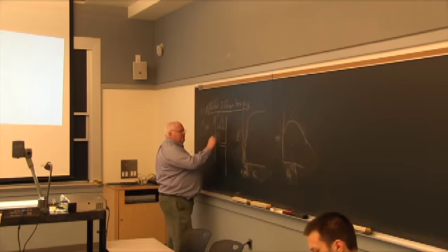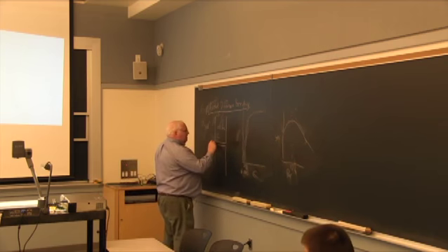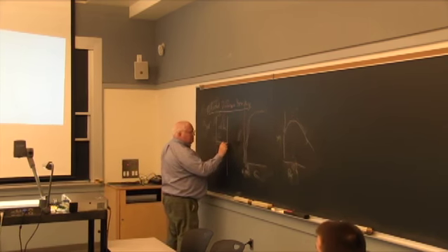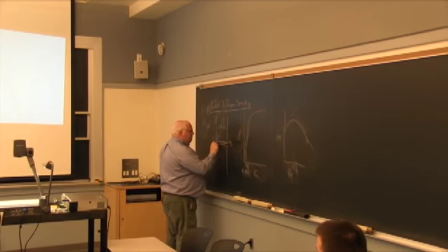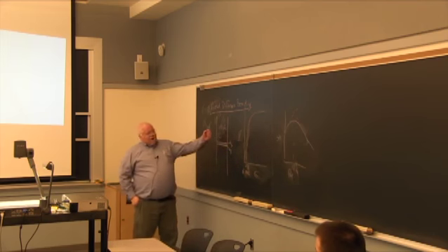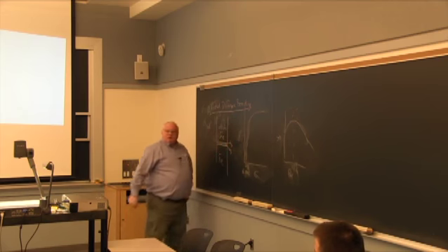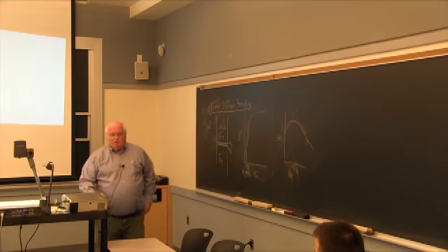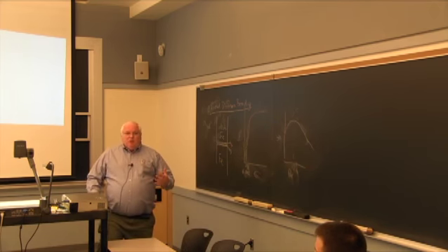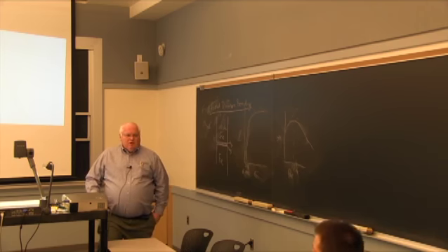And then there are other things in here rather than just iron, but you have oxides on the surface that won't let you diffusion bond at low temperature. So what O'Brien, Rice, and Olson did is they basically deposited a layer of silver on both of these. They call it activated diffusion bonding, but now you're not bonding iron to iron or high strength iron to high strength iron, you're bonding silver to silver. Silver is a relatively soft material. And silver doesn't form oxides above 400 degrees Fahrenheit. If you look at the thermodynamics, silver oxide decomposes at about 400 degrees Fahrenheit.